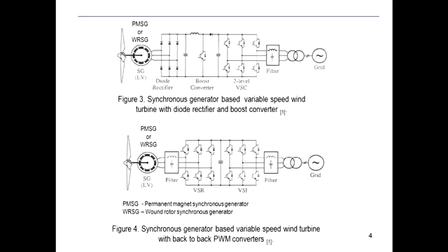Okay, but for this converter, we may have to have a power reference as well as a reactive power reference. The power reference here is the same as the power reference there, all right, because the power that comes from here will be transported, all right. If you transport less power than what you receive, then the capacitor voltage will go up, all right. So power balance is an inherent requirement, okay. Otherwise, the capacitor voltage goes up indefinitely. Okay, so that kind of issues, how we handle them, that's what we will cover.